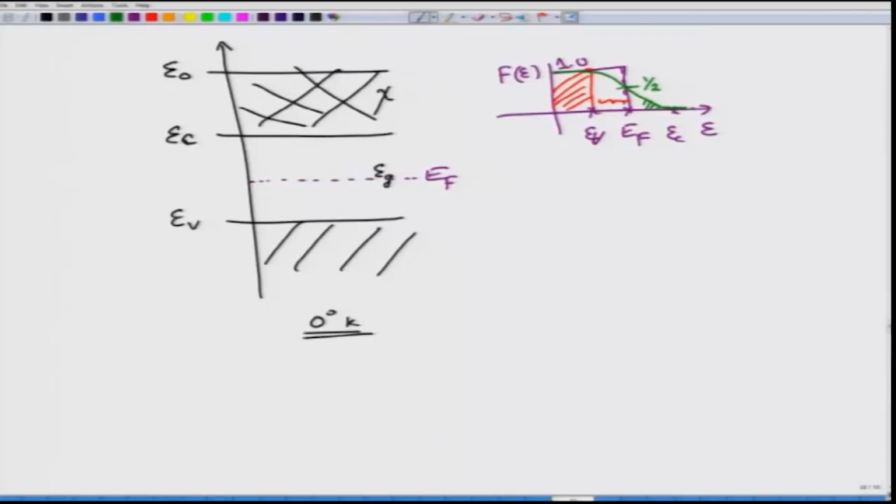It is not a real quantity when you actually look at it, but the Fermi level helps you in dealing with many of the semiconductor properties, which we are not going to look at. So, for our purposes, just remember that the Fermi level will be found, at least for 0 degree Kelvin operation, right in the middle of the forbidden region, and the existence of the Fermi level is an important topic.